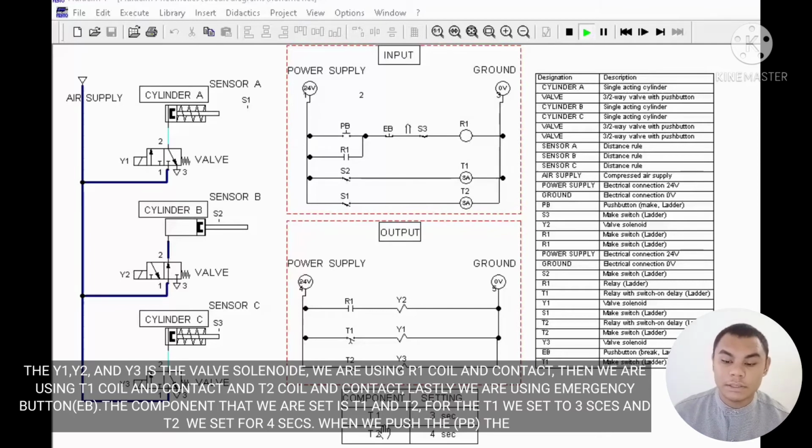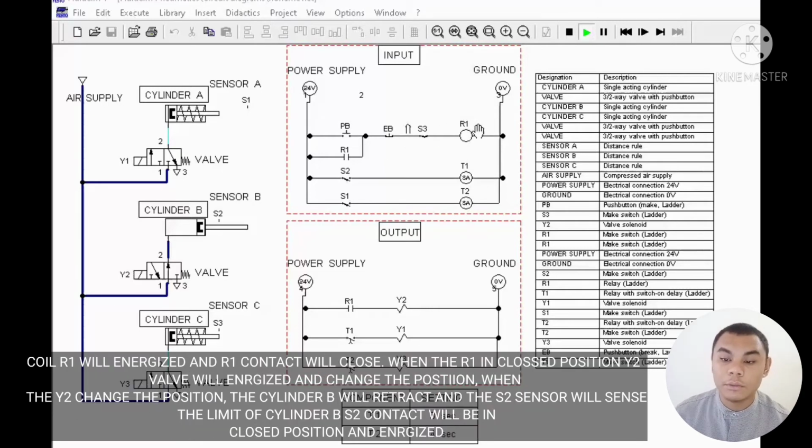The components that we set are T1 and T2. T1 is set for 3 seconds, as in problem statement 3, and T2 is set for 4 seconds. So when we push the push button, coil R1 will energize and the R1 contact will close. When R1 is in the closed position, the Y2 valve will energize and change position.